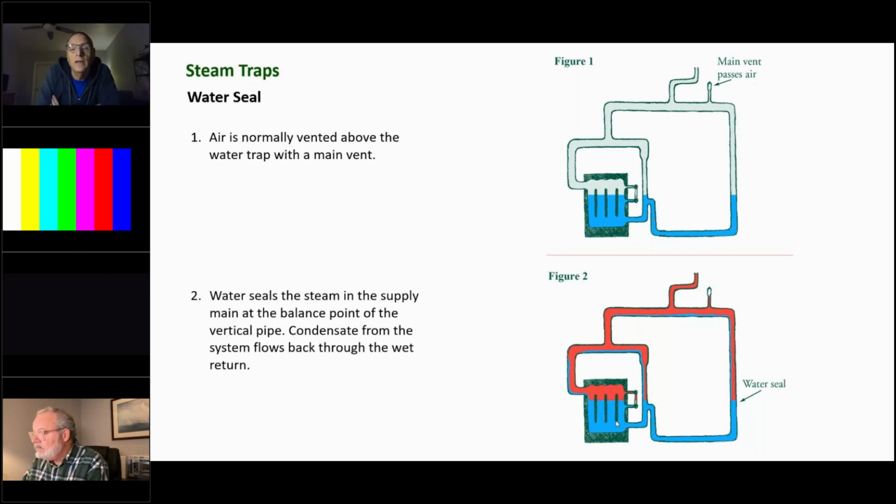You need to check with your waterworks to see if they're chlorinating the water with chlorides or chlorine. That is what kills it, and oxygen, two big killers for cast iron boilers. So probably put some type of bag filter, some type of chloride or chlorine filter on the water supply to the boiler, and then clean out the wet return, and that should increase the longevity of the new boiler.